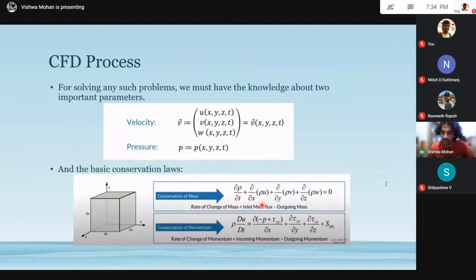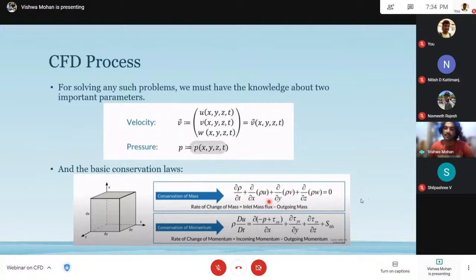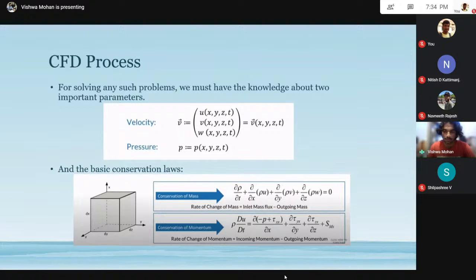And how does this represent that? So basically, it's like change of mass, dm by dt. And here in this equation, we divide everything by volume. So m by v. So this equation over here, it's actually dou mass by dou t plus the flux. And you represent the flux by a divergence, okay? So anything that is coming in or coming out.